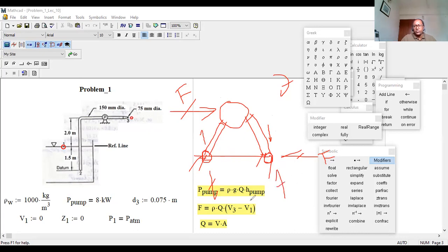So these two forces, which way do they make rotation? This is downward, this is upward, that means anti-clockwise, right? And this one makes clockwise. Anti-clockwise and clockwise, then you become neutral. So as an engineer, when you make the support, you need to consider these two forces, this force and this force, to make sure your support is strong enough. Okay. Hopefully you might understand.